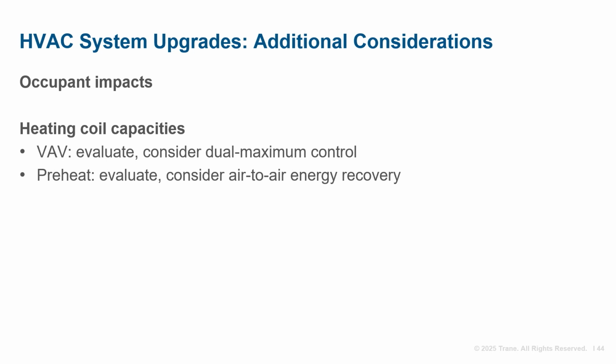Depending upon the climate, a preheat coil may still be needed to prevent frosting on the energy recovery device. We recently had an ENL on the topic of air-to-air energy recovery, and I've included that in this program's bibliography.